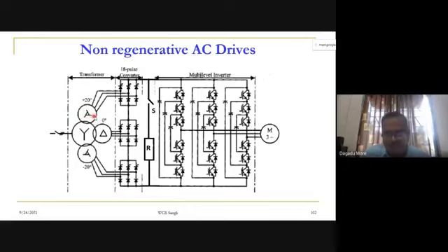Delta is there, but again it is extended, and based on that, by adjusting this extended length, we can adjust the angle. You see it here, just this here. Okay, this transformer connection group we can call an extended delta. So one extended delta will provide a phase shift of plus 20 degrees, that is, 20 degrees leading with respect to these delta line voltages.